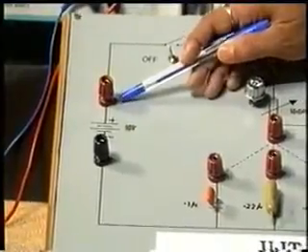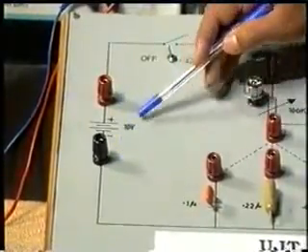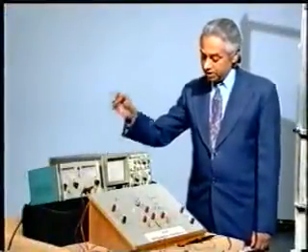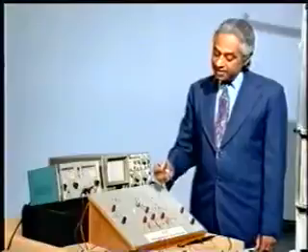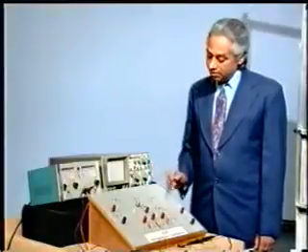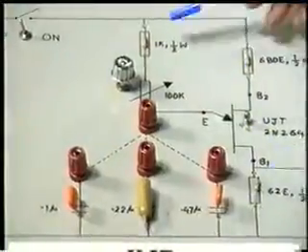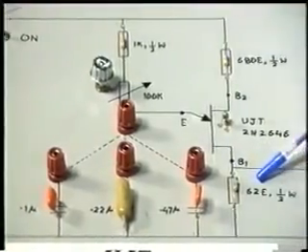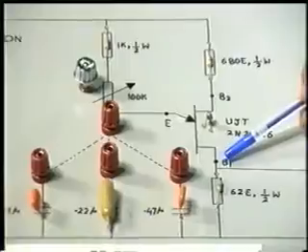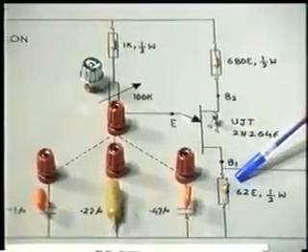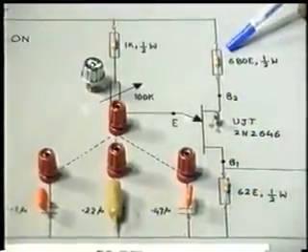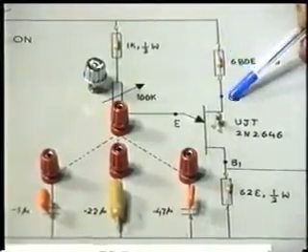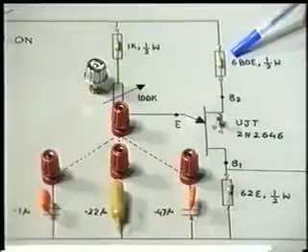This is the positive terminal, this is the negative terminal, and this 10 volt will be taken from this power supply. Now you find that there are 3 resistors. The 62 ohm half watt resistor is connected across B1, so this will act as RB1. The 680 ohm half watt resistor will be connected across B2, so this will act as RB2.